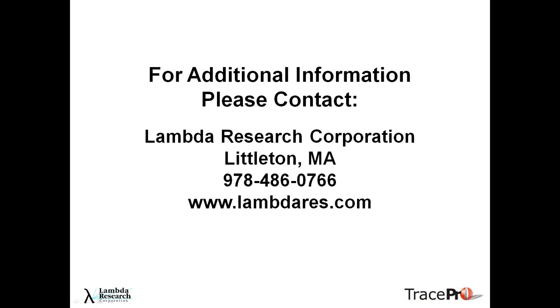That would be a good way to do it. The only thing I would caution is, if you were using, say, data from the data sheet to create your angular distribution for the LED, and that had a lens on the front of it, and then you were applying that data to the lens as well, you can in effect be double applying the property.